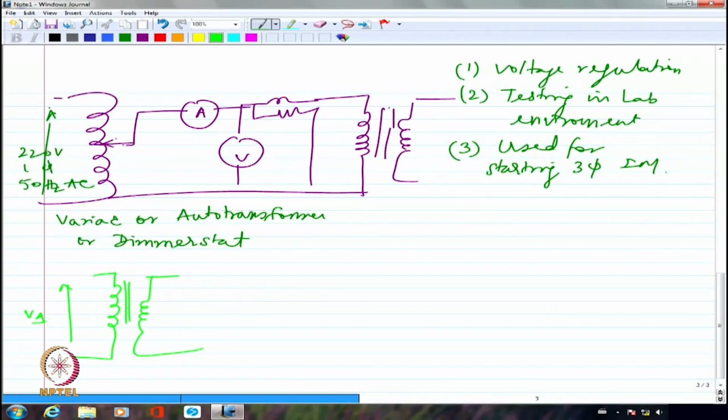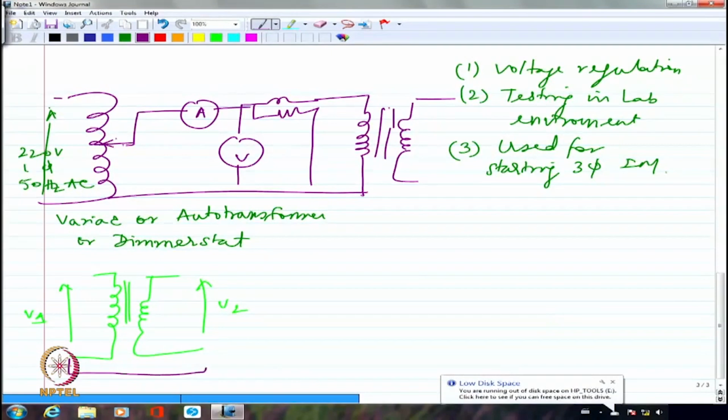Let us say now I connect these two in series. I have connected two terminals together. If I measure the voltage between these two points, between A and B, and I get the overall voltage as V1 plus V2, that means I have connected them in series addition. If I get V1 minus V2 or V2 minus V1, whichever is higher, that means I have connected them in series opposition. I hope you understand.